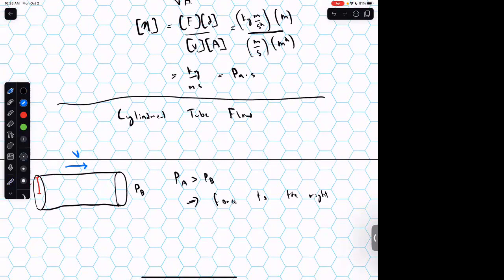Okay. So if I'm driving a fluid through a cylindrical vessel, a cylindrical pipe or something, it turns out that if I look at what the fluid particles are doing, not all of them are actually traveling at the exact same rate through the pipe. So if I measure the cross-sectional velocity or speed through the flow, usually the way it looks is that fluid near the wall barely moves. It's called a no-slip boundary condition. But as I get closer to the center, I'll see that the fluid moves more and more.